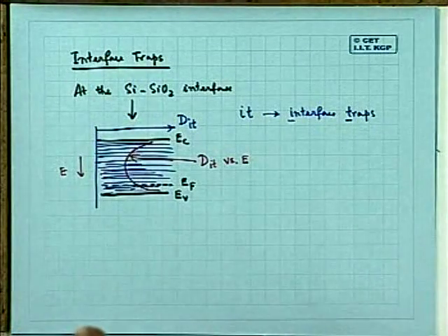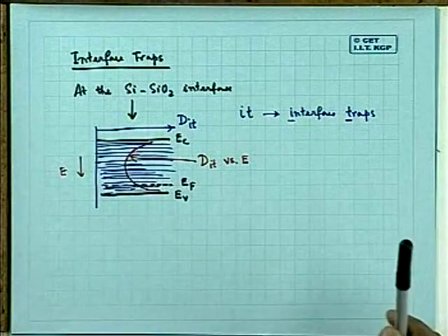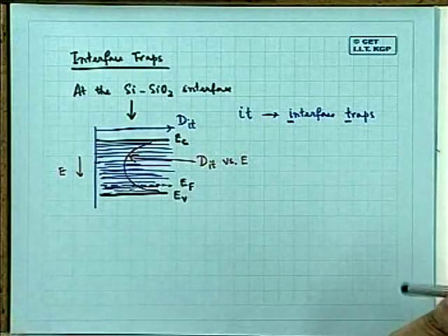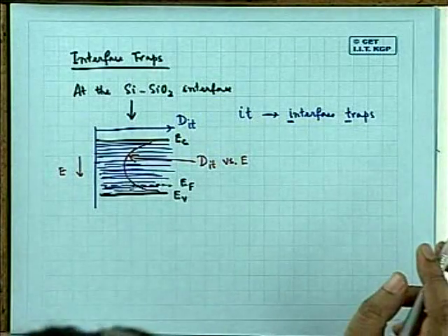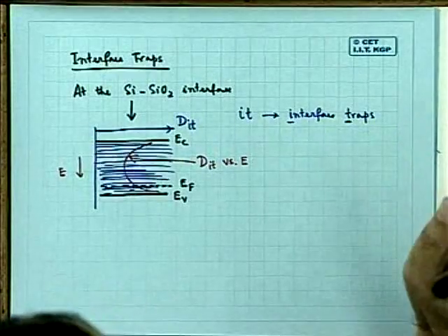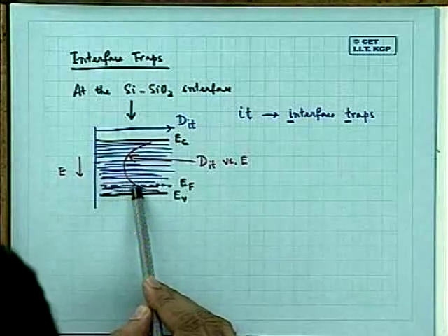So what is going to happen? Up to the Fermi level, according to our Fermi-Dirac statistics, all the states will be occupied. Above it, it will be empty. At T is equal to 0 degree Kelvin, that is perfect. Even at 300 degree Kelvin, semi-perfect, which I discussed earlier. So up to EF, all states will be filled up.